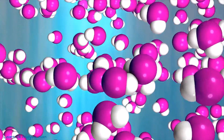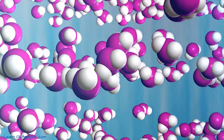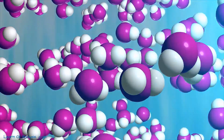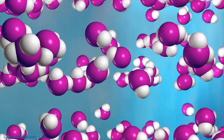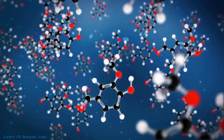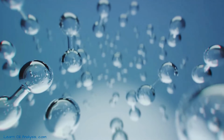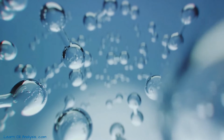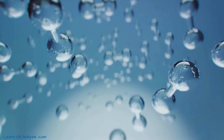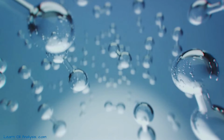Lastly, we have high energy discharges, categorized by extensive damage and carbonization. Here, the oil undergoes severe thermal cracking and pyrolysis, leading to the release of a variety of gases. Remember, these are not isolated events. Multiple faults can occur simultaneously, or at least one fault can lead to others, resulting in a complex mix of gases. It's the art of interpreting these gas combinations that makes dissolved gas analysis so crucial for maintaining the health and longevity of our transformers.